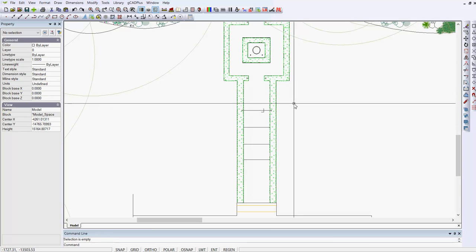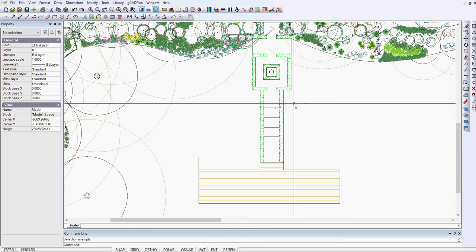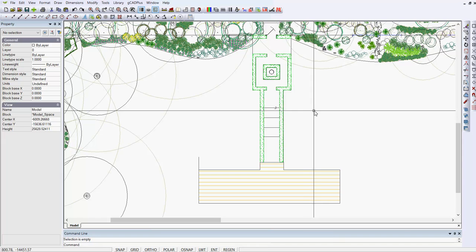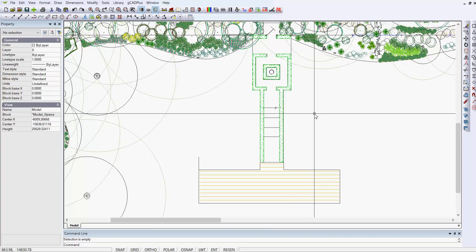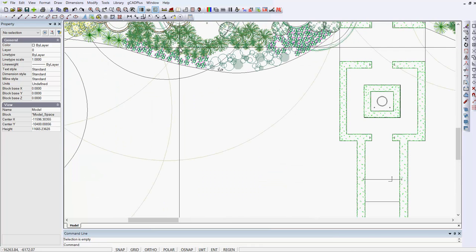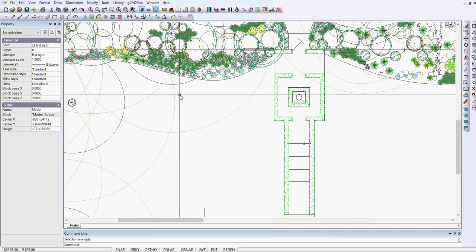If I zoom in this area here, all the way along here are thousands and thousands of individual entities, and they need to be removed and the hatching done in a different way. The take-home lesson here is don't explode hatching, because it just complicates things enormously, and if you are going to make symbols, make them much simpler. These symbols are far too dense, but I digress.